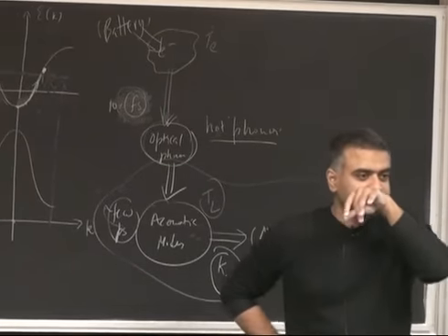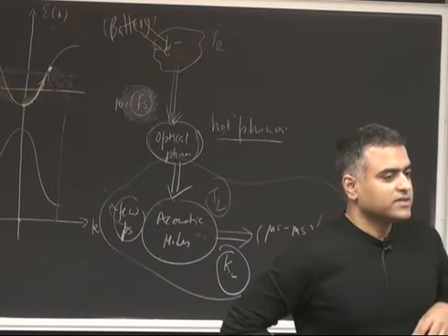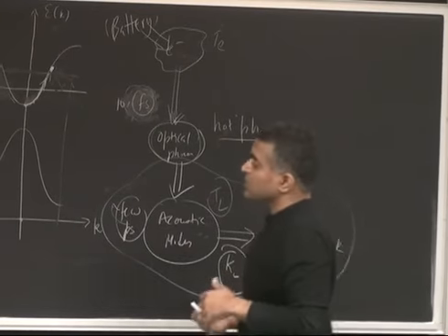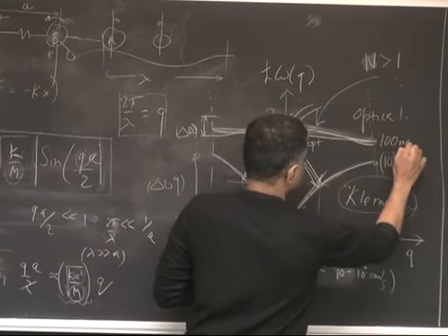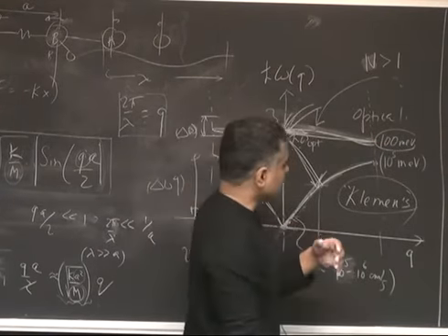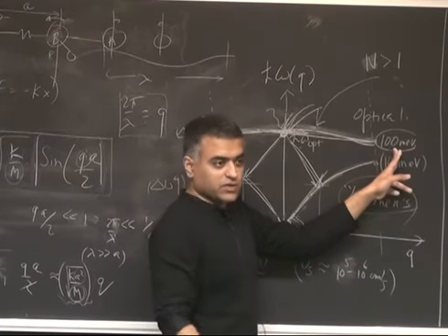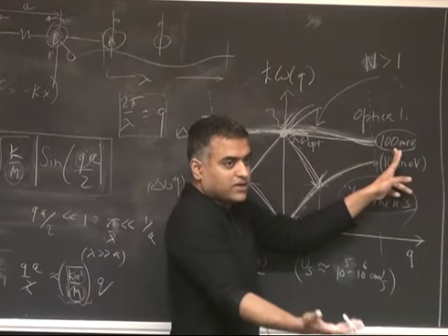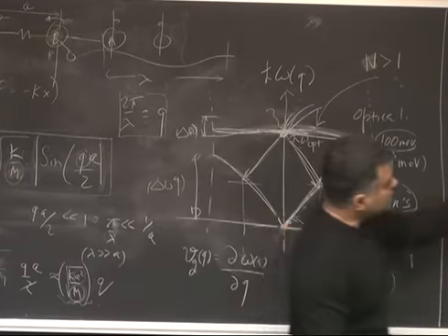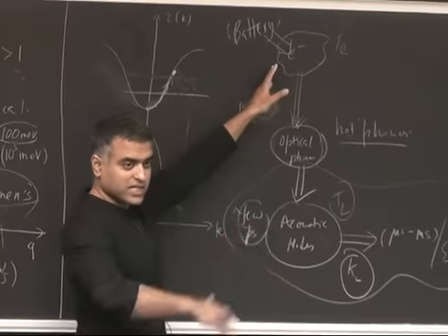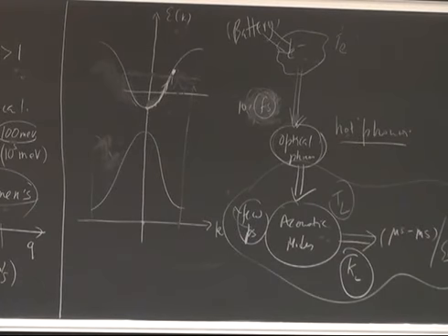Yeah. So if the battery doesn't give enough energy to the electron, it will skip the optical phonon. Yes, good point. Let's look at a concrete example. Take aluminum nitride, where the optical phonon energy is about 100 millielectron volts. Let's say you have a battery and you are applying only 0.05 volts, because 100 millielectron volts is 0.1 volt. You're only applying 50 millivolts, so even the highest energy electrons don't have enough energy to excite this. In that case, you will not excite this at all. You will only excite these modes. So this is more of a very high energy, high field phenomenon when you saturate. At low fields, electrons essentially emit into these modes, and that's how you reach equilibrium.